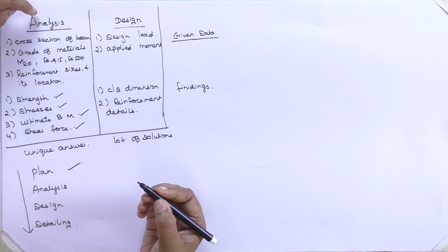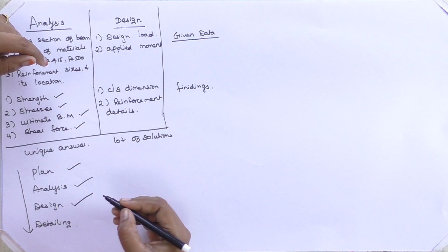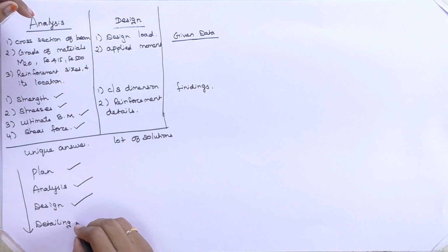First thing, we need to plan your drawings according to your client's consideration. After that, you need to analyze what type of stresses will be carried, for some assumption of the cross section of your elements provided beforehand. Then after assuming the cross sectional dimension, you need to check whether those assumptions satisfy your design part. After that, you can provide some reinforcement. From the reinforcement, you can detail your drawings so that your structural design will be completed.